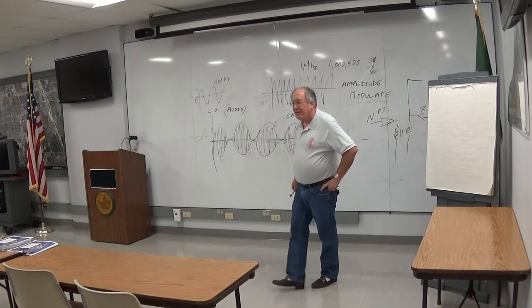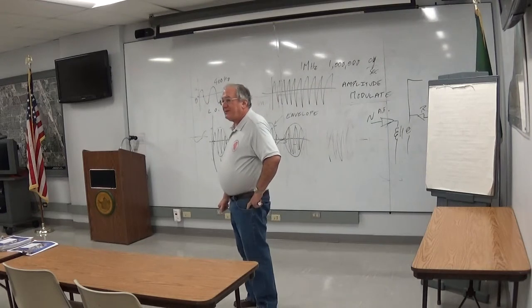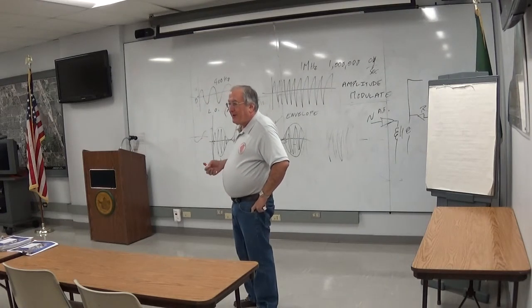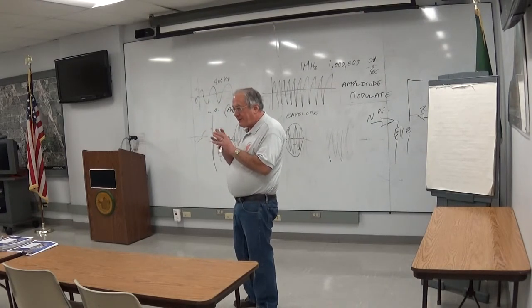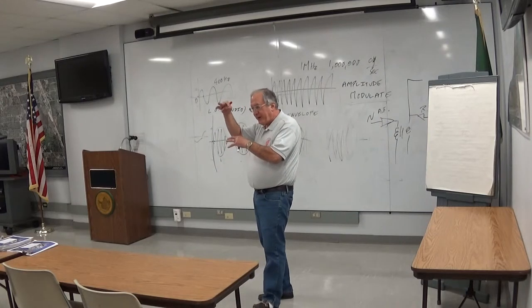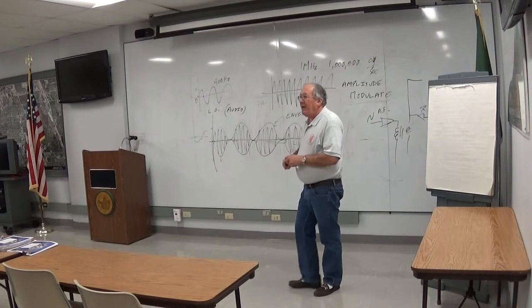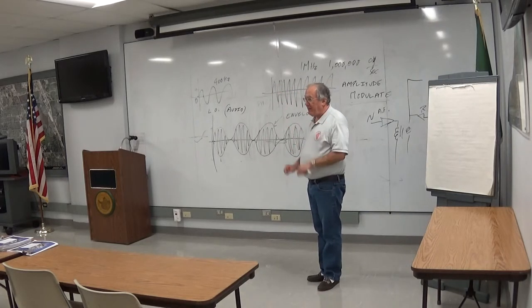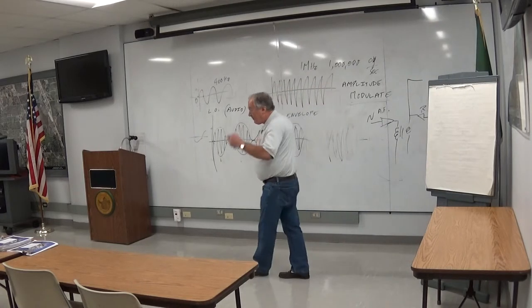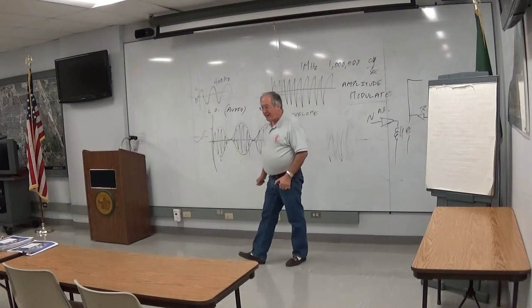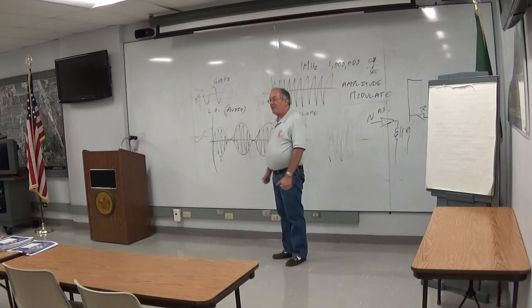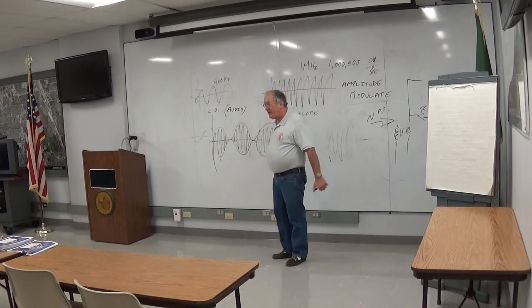As a result of this, fancier and fancier CB radios came out. Some of them had a pre-amplified mic with some wave shaping software that would pre-emphasize certain parts of your voice spectrum. And they refer to those loosely as a modulated mic. It's not a modulated mic, it's a mic with a preamp and a filtering circuit to do some shaping of your voice pattern.